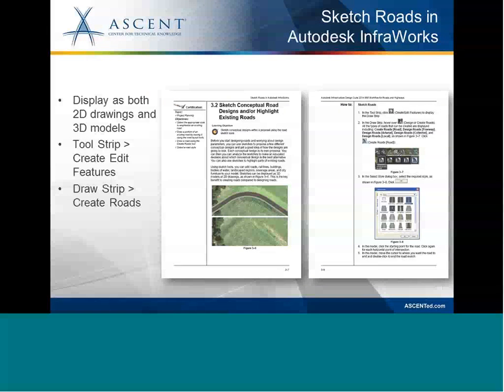Then when you get into sketching, it actually helps you understand the difference between sketched roads and engineered roads. The benefit of a sketched road is if you do need to show 2D plans, you have the option to show the 3D model, which gives you a nice road with stripes and everything, or the 2D model that has just the line work.